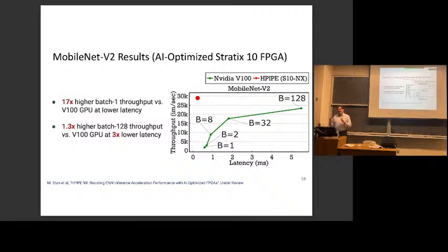They basically have more multiplications, but they're lower precision. So instead of having two 18-bit multipliers in every DSP block, you can get 30 8-bit multiplies in that same DSP, in what they call a tensor block. So you get more multiplications, but they're lower precision. And there are some restrictions on how you have to use them, which I'm not going to get into right now. But by changing that generator, that domain-specific compiler, to understand the restrictions of this architecture, we're able to use those tensor blocks well.